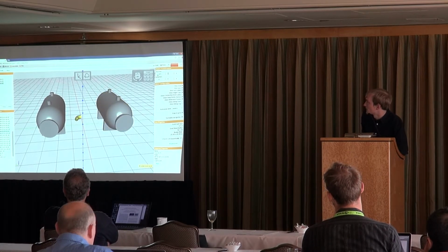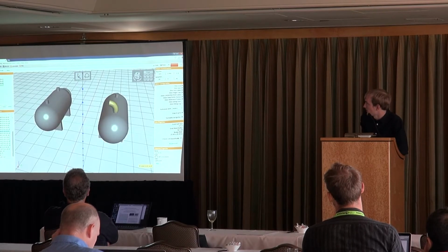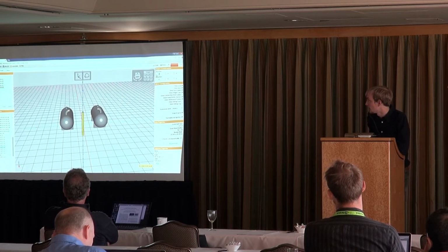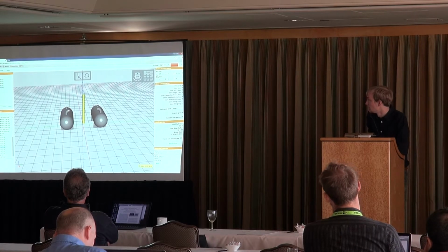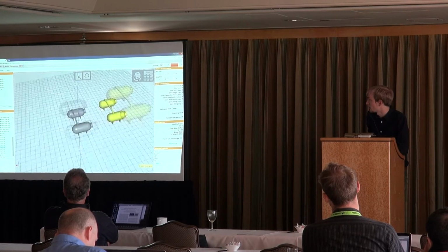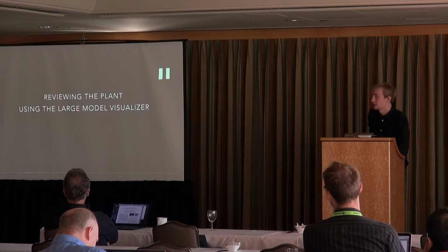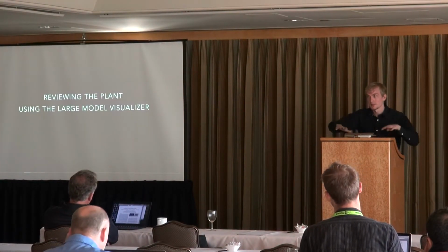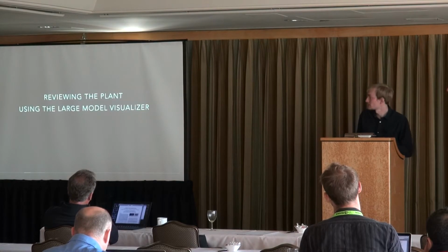And then we select some elbow components, place them there, and select both of them by adding a pipe. You can of course group the whole thing and clone it again. In this way you can quickly create a spatial layout of your plant structure for planning.